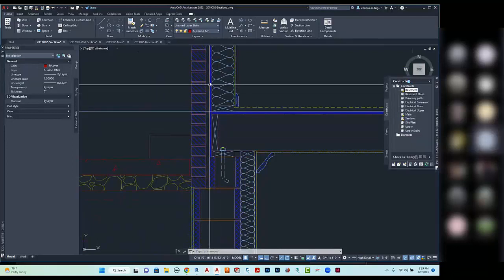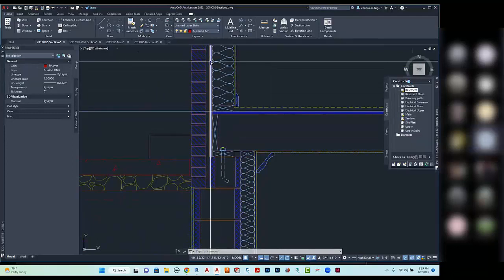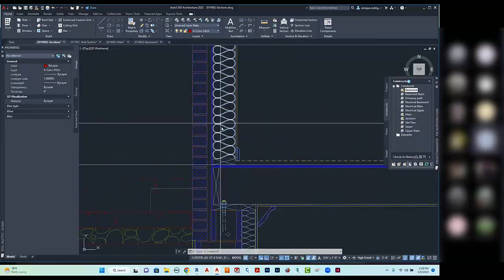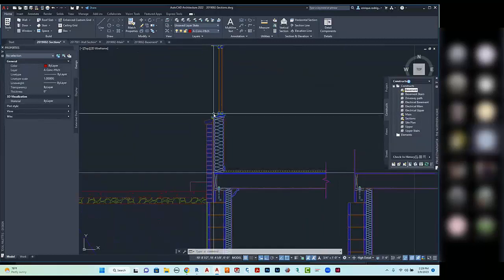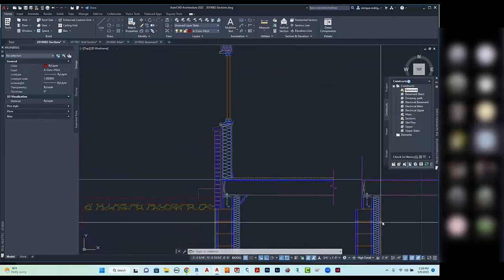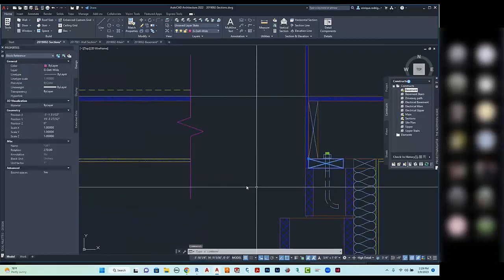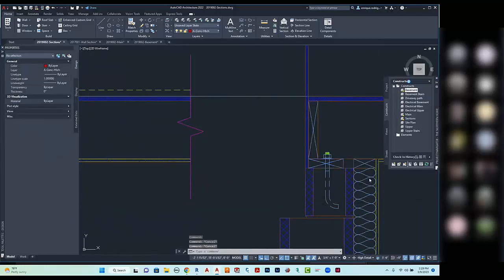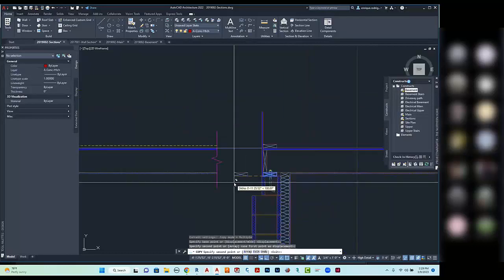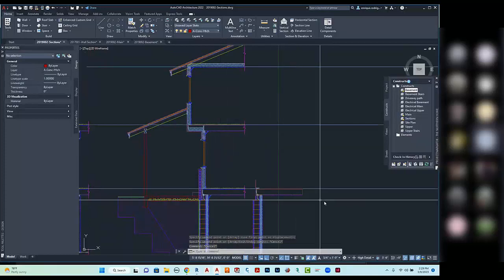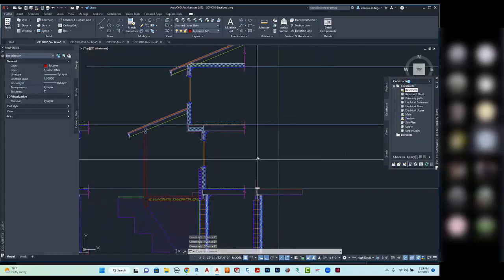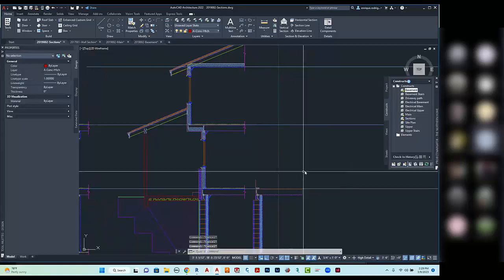So we had already stretched this plywood sheathing on the outside vertically a little bit. So what we're going to do is start the wall on the main level. We know this is a 2x6. We've already put in a 2x6. Let's go ahead and copy this. Pull that up to here. And we know that this 2x6 wall is going to go up to 8'2".